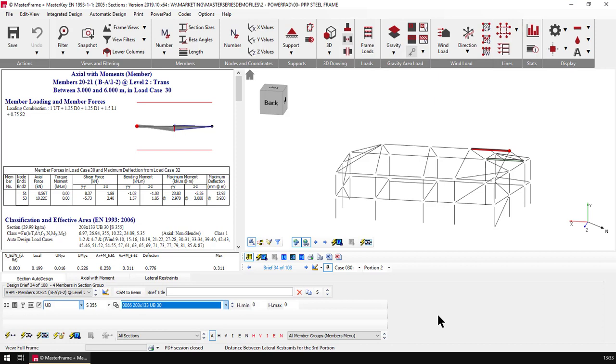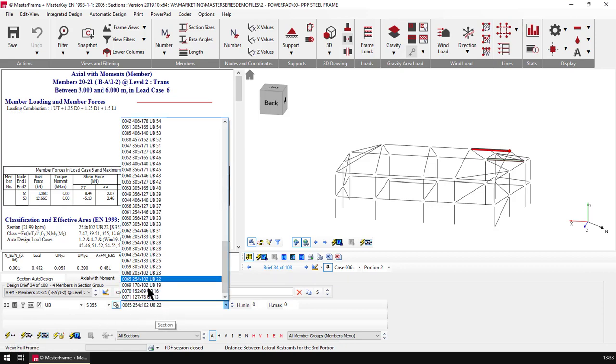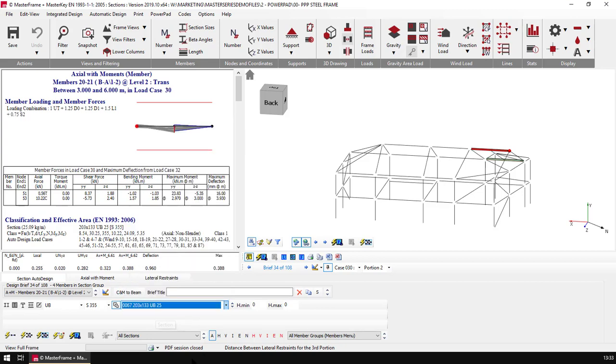And of course we don't have to do those choices all ourselves. The software, like all good software, is fully automated. We can just hit the automatic and it's giving me the shallowest beam. If I turn on weight order and hit automatic, it's giving me a slightly deeper beam that's going to work. But in my case, no, I prefer the slightly heavier squatter member.